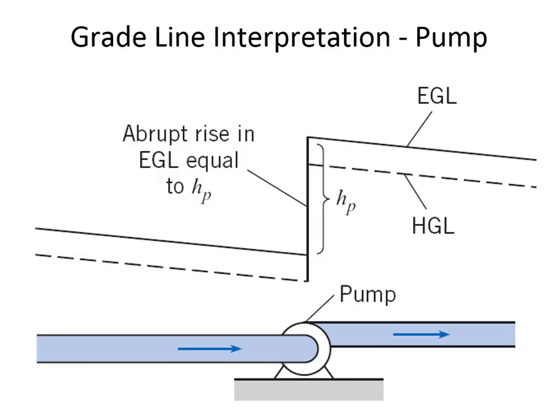And that's another way we know that the pump didn't speed up the water from inlet to outlet. The pump added pressure. And one of the representations of that is the fact that this gap between EGL and HGL is the same. And the pump just simply boosts up the energy on the outlet side. And then as water flows through the pipe, it's sloping downward, downward, downward as the pressure gradually decreases. Any questions about drawing these lines so far, or how to interpret them?